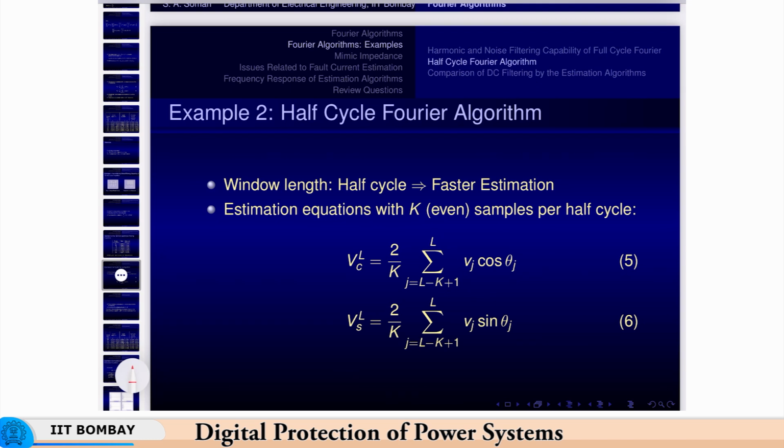Now, as we said, all our computations, like distance or even overcurrent, they have to wait for the phasor estimation to be complete. Okay. So, we have to wait one full cycle for it to be complete, and where very fast relaying decisions are needed, can we do something to reduce this time as much as possible? We will see what the trade off is in terms of the accuracy.